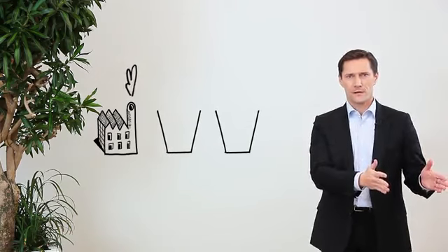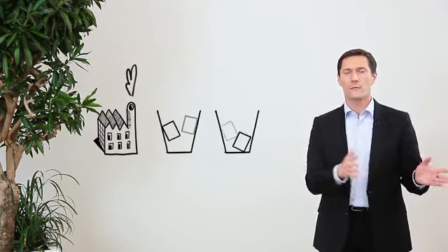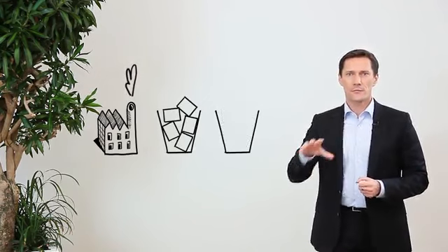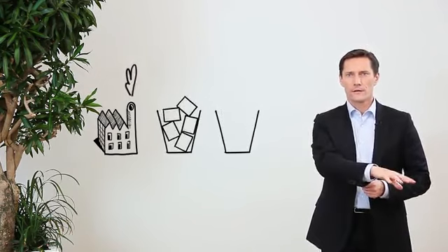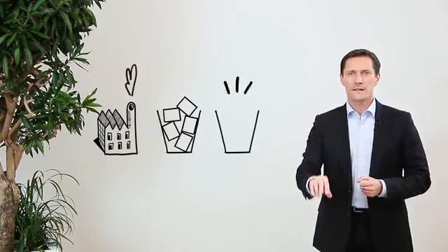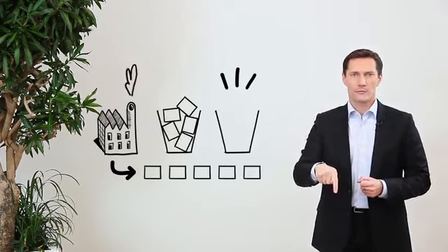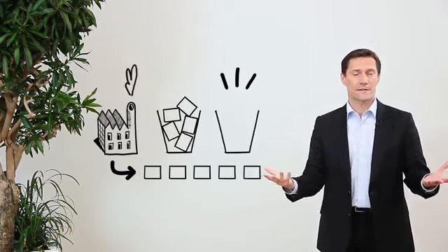There is one easy example for a Kanban. It's called two-bin system or two-bin Kanban. So you need to imagine you have two bins. At the beginning, both of them are full. Now I take something away, so it means I have an empty one and a full one. And the empty bin is a signal for the replenishment product to start to produce and replenish the product. That's an easy thing.